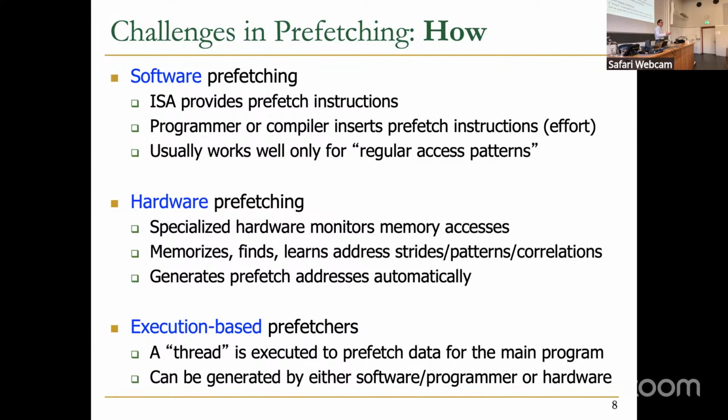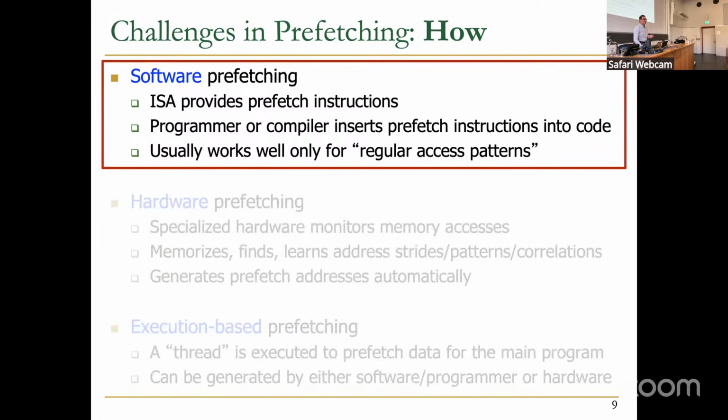You've seen row buffers, you've seen DRAM. So it's good to think about that right now. If you're prefetching, and if you have demand accesses, these can conflict with each other potentially. And if you want to get good DRAM bandwidth, you may want to reorder the accesses. Okay, so there are a lot of interesting things here. Any questions?